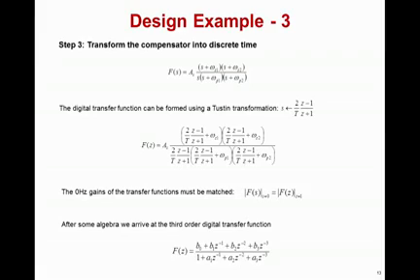This can be done by setting each equation, both the F of s and F of z, to 0 and solving to determine the value of the offset between the two. The equation shown at the bottom of the slide is what is typically shown for a digital compensator in the third order, like we saw originally from the type 3 in the analog domain.